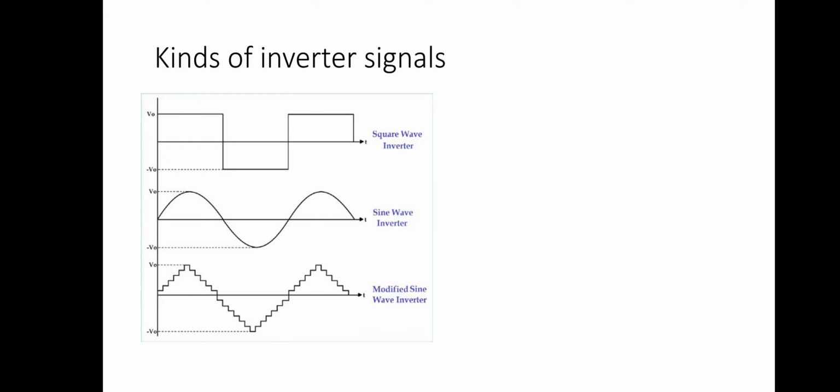Now this kind of signal gives your inverter a noisy sound, especially when using low frequency transformers. You will hear the inverter making a kind of buzzy sound, zzz, on the inverter system. Why? Because the signal is not smooth. Now, the side effect of such kind of inverter is when they are connected to inductive loads, for example your standing fan or your ceiling fan. You will notice that the fan will begin to make some kind of noise when connected to such kind of inverters.